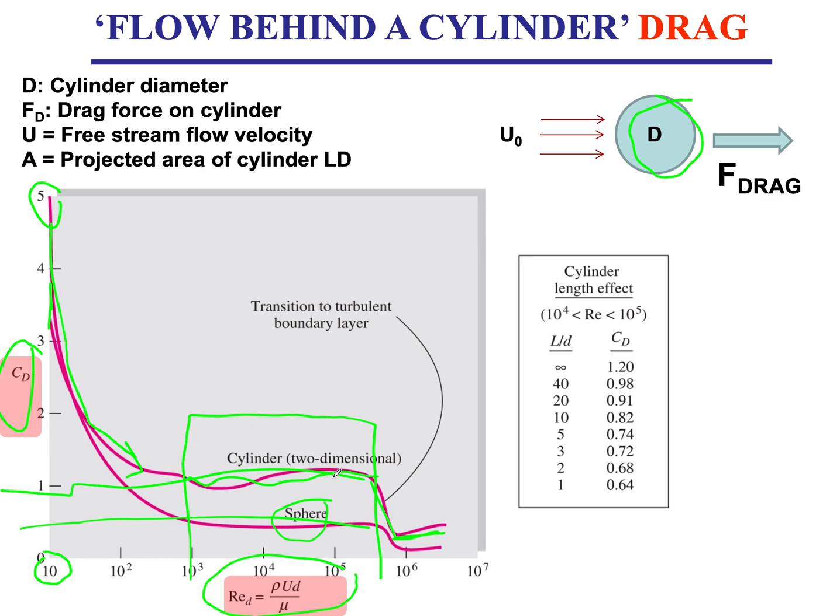But of interest to us is this particular region where variation of Reynolds number does not affect the drag. But as our Reynolds number is very small, the drag coefficient is very highly dependent. The drag coefficient drops very fast at low Reynolds number, because in the non-dimensionalization of the Navier-Stokes equation, here we had creeping flow where the effect of viscosity is very high, and as your Reynolds number gets higher and higher, viscosity becomes negligible and the flow is inertia dominated.